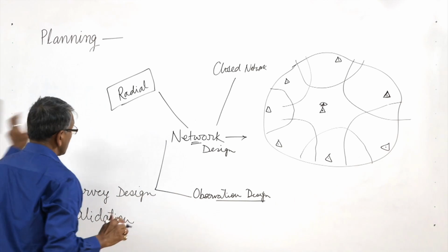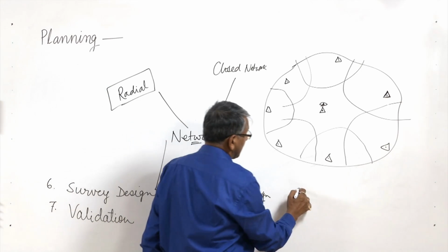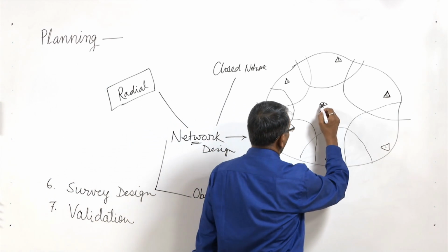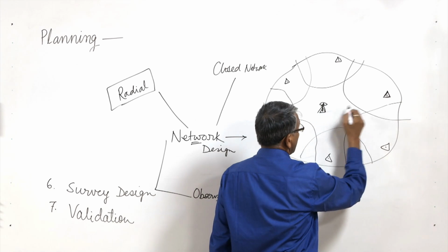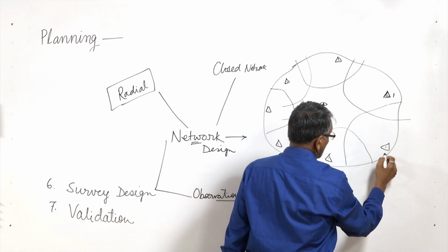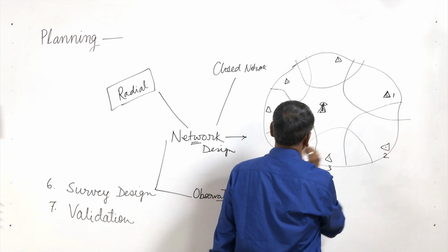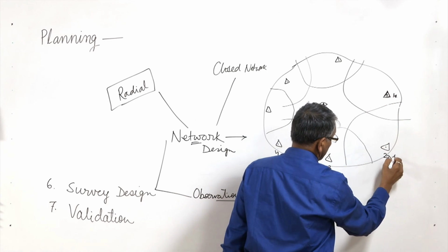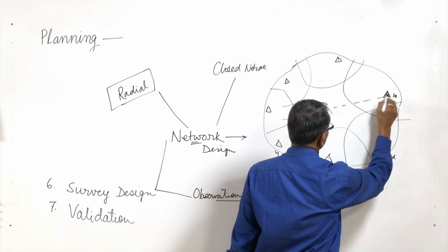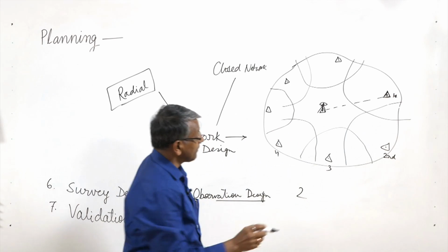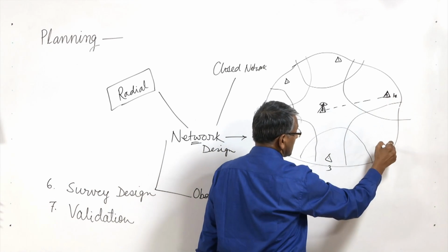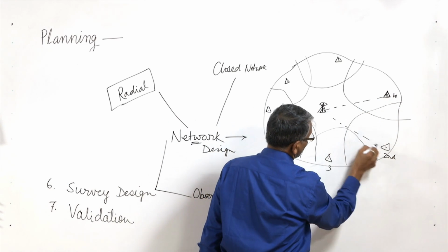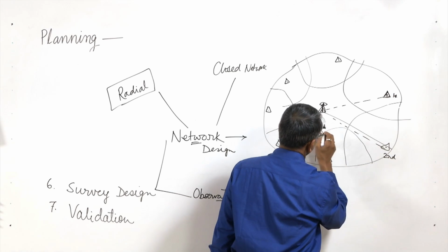One of the methods is the radial method. Suppose we have 2 receivers. Then one will always be placed here at the center, and the other will be placed first at station 1, and I will take the reading between these two. After some time I will shift it to the next, and take the reading between these two, this is the baseline.